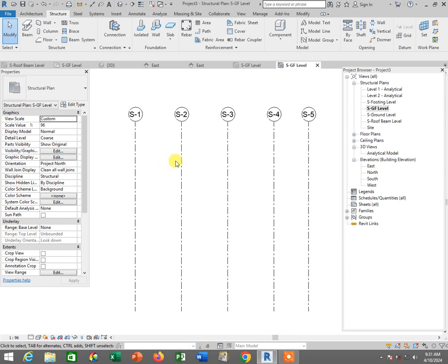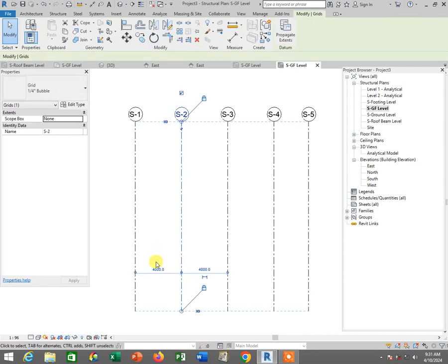the location of the grid, the distance is different. You can re-enter back its distance by clicking one of the grid. So I can click on this parameter to edit back its distance length. So if I were to type 3000, it'll update and relocate back the location of my grid.